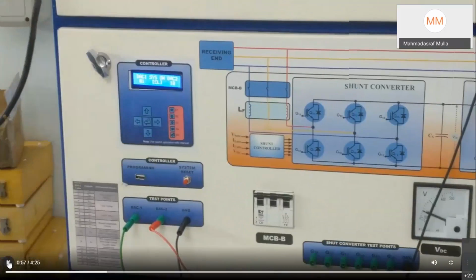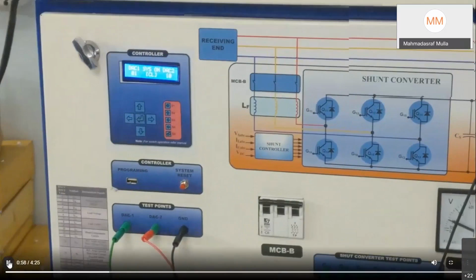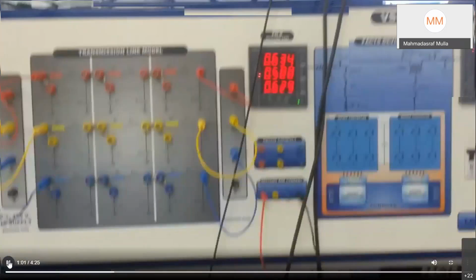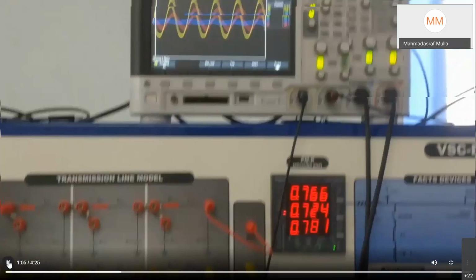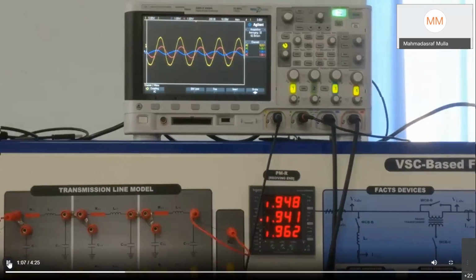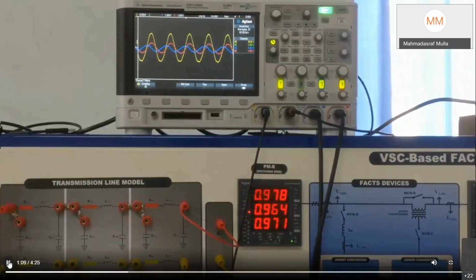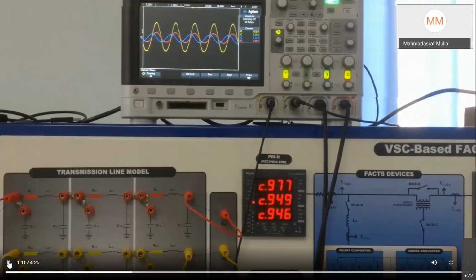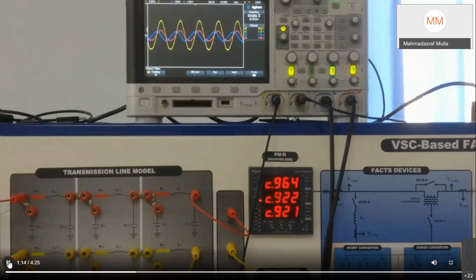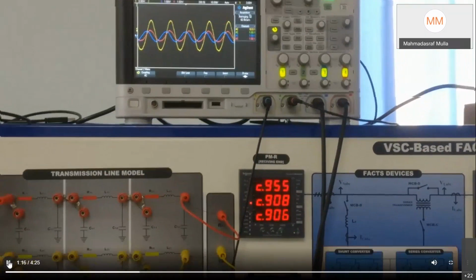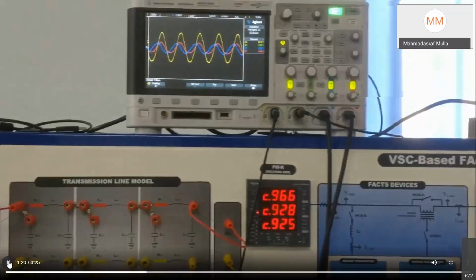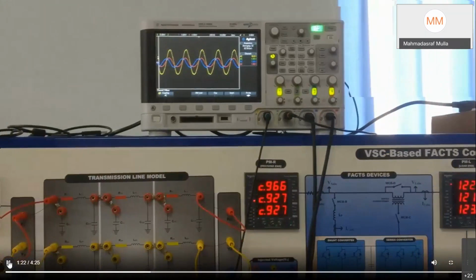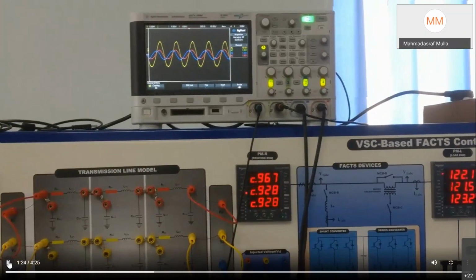As you can see, it is showing that the system is on. Now it will gradually increase the DC link voltage and gradually increase the compensating current. You can see the blue waveform over here is the compensating current. We have taken the compensating current using DAC.